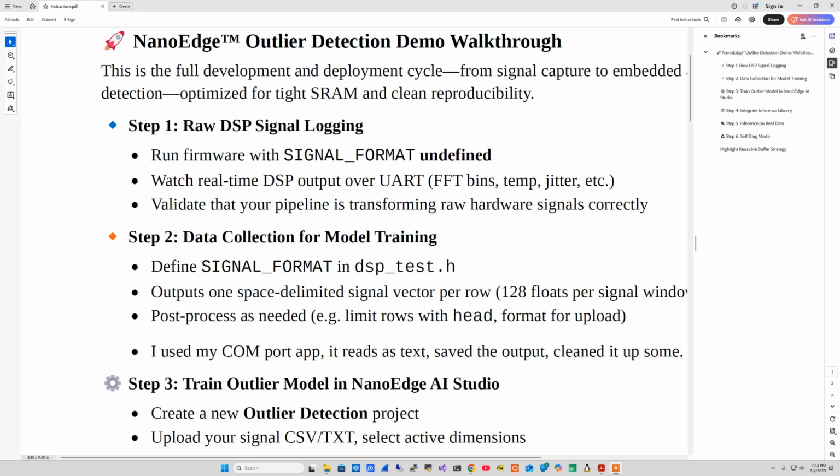application. So it features a reusable buffer architecture to reduce SRAM and so you don't blow your stack and so on. And then also for testing, I have a very big two-dimensional array, but I have that conditionally compiled out. But even when you compile it in, I use the const qualifier so that it ends up being in the data section, in the SRAM. And then the reusable buffers kept me under 4 kilobytes buffer usage for the entire application.